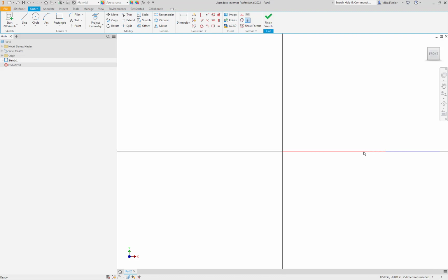So you'll notice what I did there was two different sketch segments. The reason that I did that is because Nastran will convert these sketch segments to beams, and anywhere where you start and stop the sketch line, you will end up with a node in your mesh or a point vertex in your mesh, and you can utilize that to apply your load. So that's why I create a line. We can add our load and then another line segment.